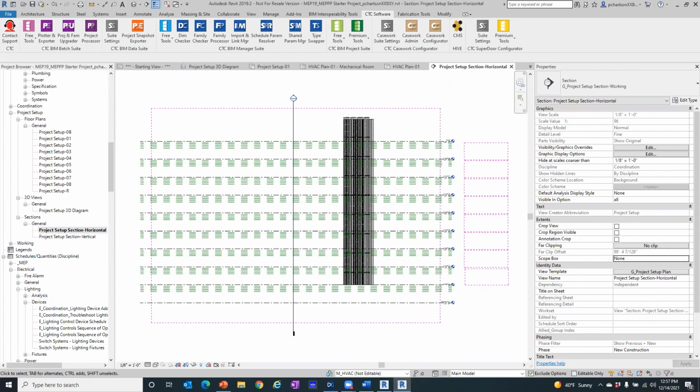As far as families go, I try not to deeply nest other families within it, just because it makes the overall family size that much larger. And if you are putting that in multiple times into a project, it can make that project pretty good size. In some instances, you may want to look at using the grouping tool instead. If you group those items, those can be scheduled individually as components. So that is an option that you may have there.